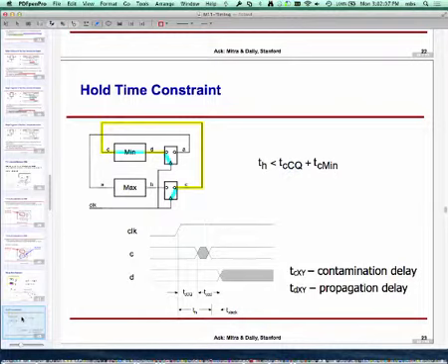other than, what? So how would you fix this problem? Let's say you see a hold time violation. One strategy is I pick flip-flops which have a smaller hold time or even negative hold time. What else can you do? Increase the contamination delay of the combinational part. Increase, yes. How would you do that? No, register. Remember, the right hand side is all combinational logic. So there's no register. Register is a flip-flop. Could you line up enough NAND gates or something that has some delay? Exactly.